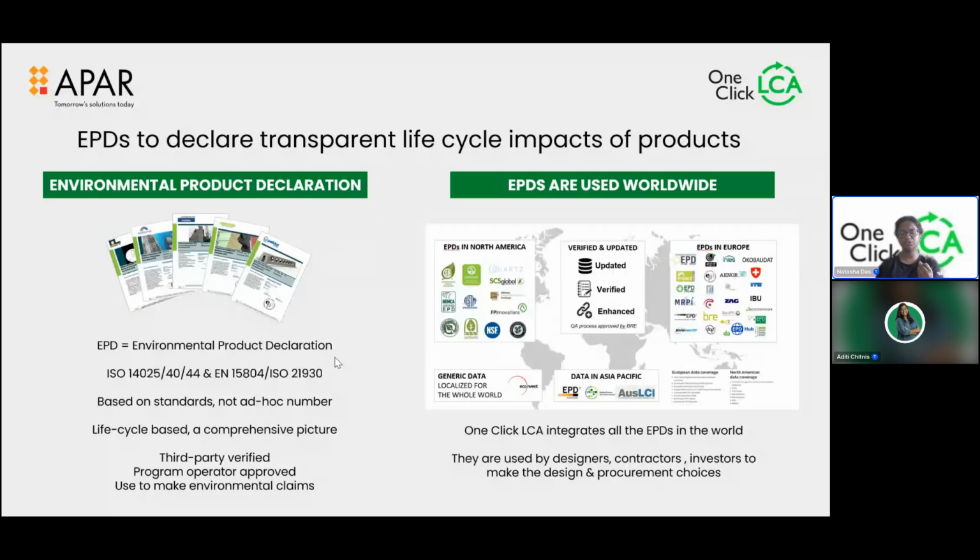All of this information has to be declared in your EPD if you are producing the EPD to be used in France. They have their own database. It's called INEAS. Similarly, I believe even for Netherlands, there are certain additional indicators. So you have the 12 indicators according to the EN15804 plus A2. Along with that, you have an additional table of other additional environmental impacts. So you might want to look at that.